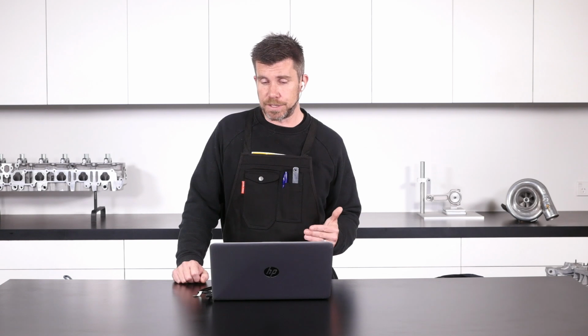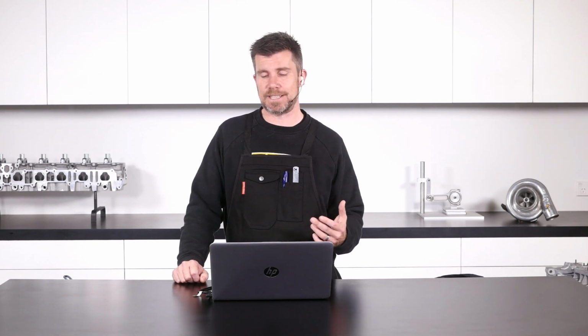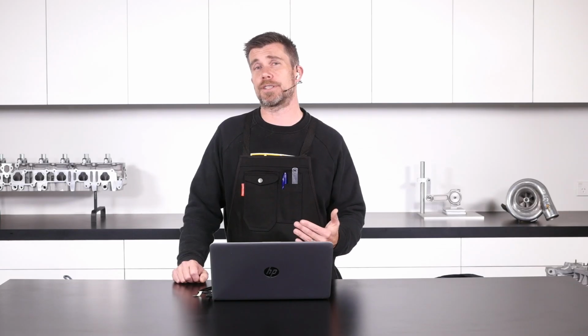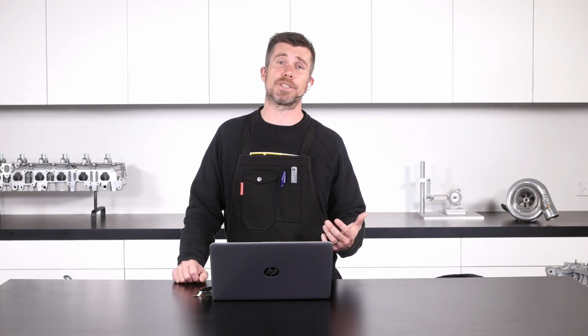What I would suggest, because they are quite a specific setup here, is to use this as a conventional Alpha-N style, where your fuel table is RPM versus throttle position. You've got even an overlay or a target air fuel ratio table related to manifold pressure, so you can trim your fueling targets as boost pressure changes. Then you could, if you wanted to, bring in exhaust manifold back pressure as a compensation table.